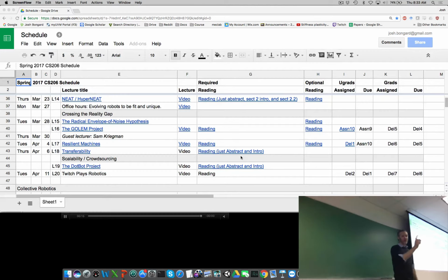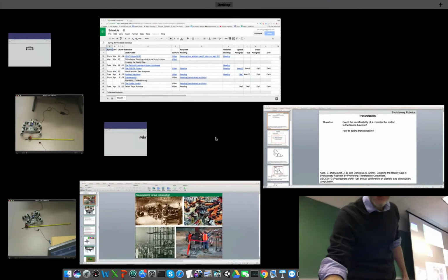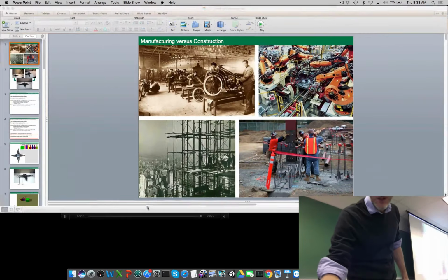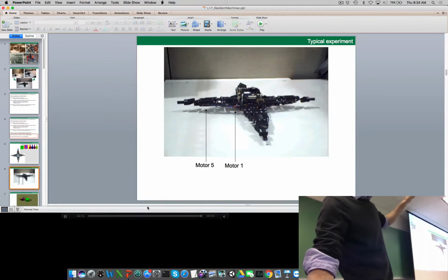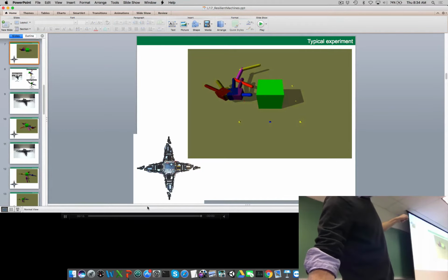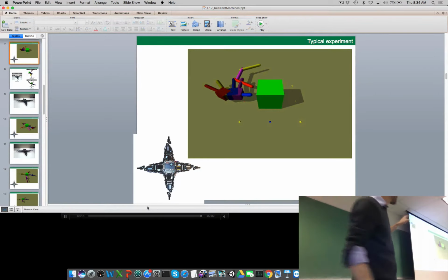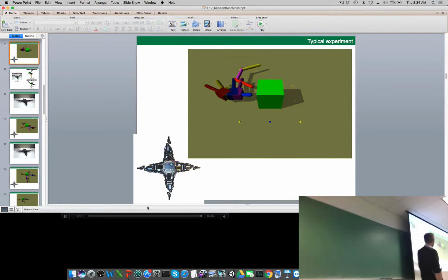And we did this by going back and forth between the physical robot and the simulated robot. The physical robot performs some random action, and it knows that when it performed this action, it gets this sensor data. It runs that first evolutionary algorithm that evolves a population of physics engines, and it's actuating, or running, that controller it just ran on the physical machine on the virtual robot. And the fitness of this virtual robot in this physics engine is calculated how? How do we know how accurate this simulator is?